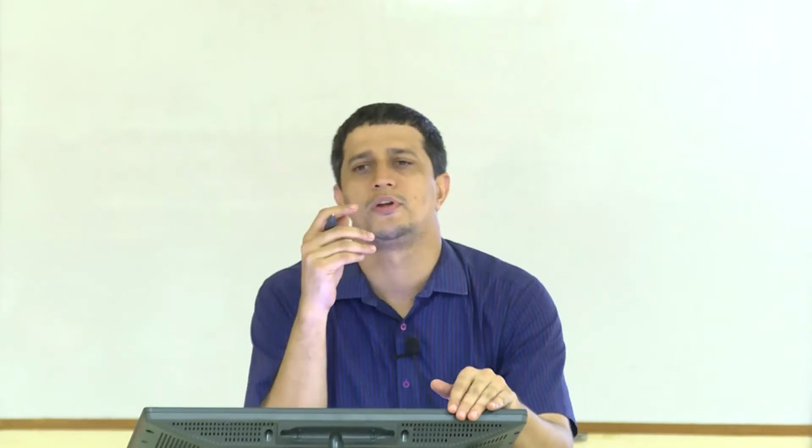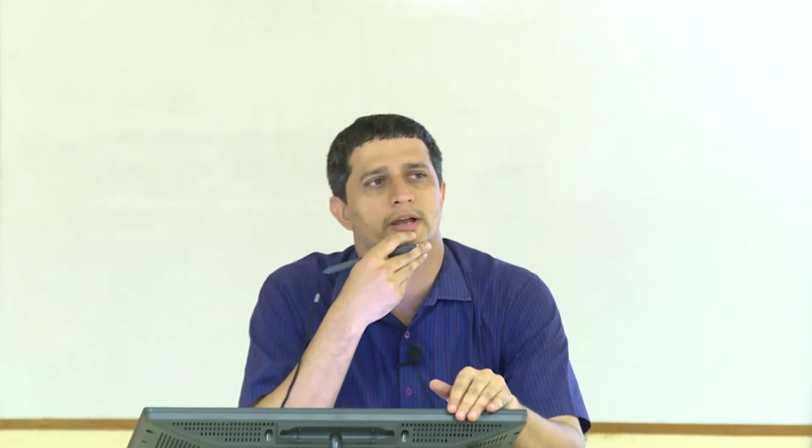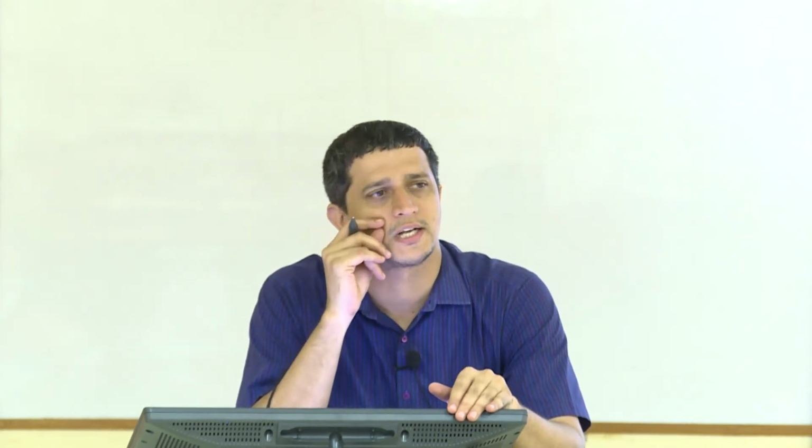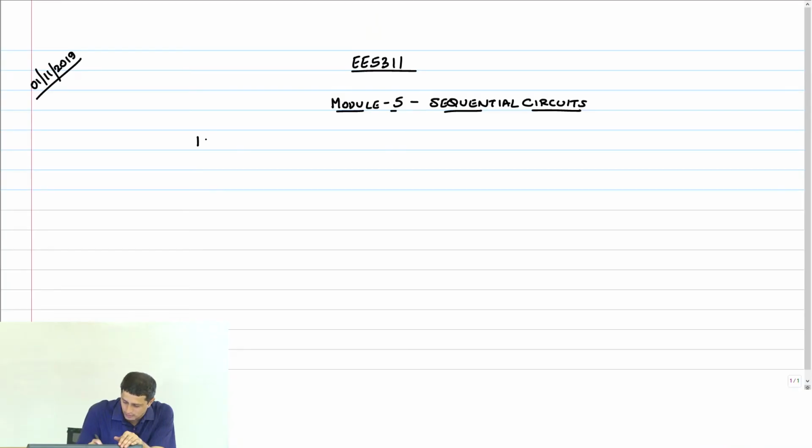So let's get going here with the discussion on sequential circuits. Last class we were discussing the idea of a latch and a flop. A flip-flop is also called a flop, right? So this is level sensitive and this is edge triggered.